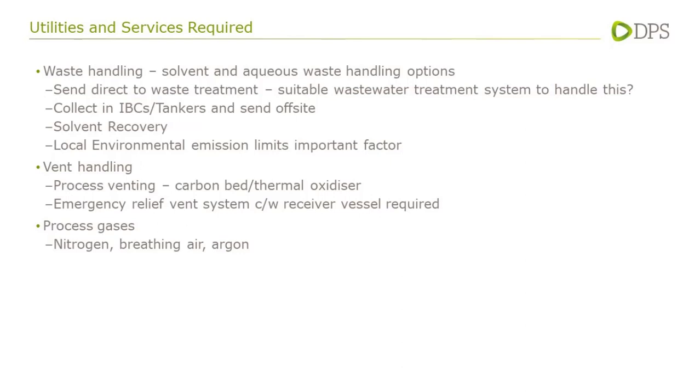Separate columns are required for acetonitrile and toluene recovery, if they have been segregated correctly when they were collected at first. Usually the biggest obstacle to utilising recovered solvent is that it involves a change to regulatory filing. So preemptive recognition in the filing of the possibility of using recovered solvent can save a huge amount of time and money.